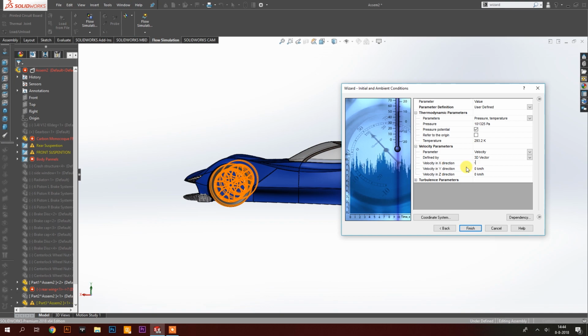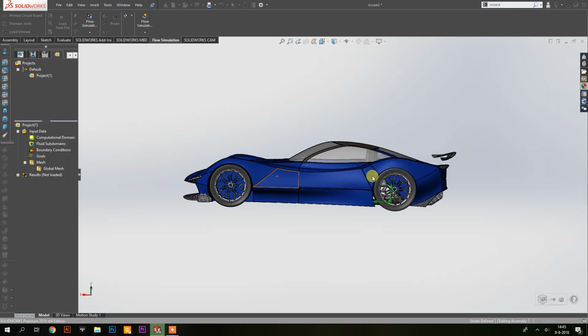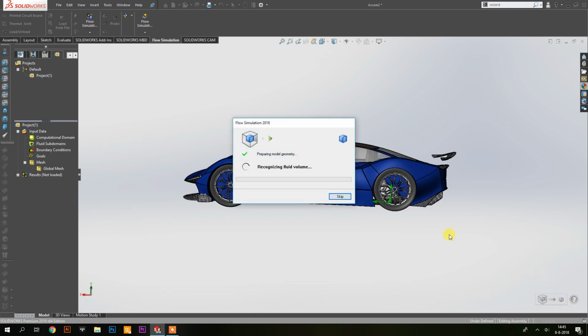250 kilometers an hour is a bit of an industry standard which a lot of people try to use for the aerodynamic test. That is always the test standard for downforce. If you hear quotes about kilos of downforce being generated, usually it is at 250 kilometers an hour. So that is what I will use as well. And then this gray box will open on the car, and you will also see this little box right here, and I will tell you about all of those things. But maybe it's just good to do it right now.